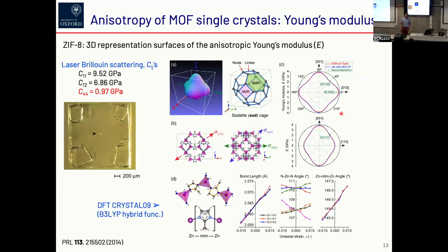Now, to study anisotropy more closely, because in nanoindentation you're actually probing the solid in three-dimensional space. So the response is more of an average than unidirectional or uniaxial in that sense. So one of the studies that I did, this was way back. This reference is actually wrong. This one was a work from 2011 earlier. So it was using laser Brillouin scattering. So the single crystal sample is just down there where my red dot is. The thickness is only 100 micrometers or less.